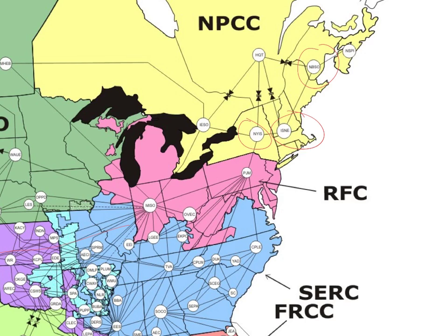What this map doesn't show, and it does show a DC line, this actually doesn't go through Maine. It actually stays above. But right up in here is not ISO New England territory. That is Northern Maine ISO, managed out of Bangor. So there is no direct high voltage connection, 115 or greater, that goes from ISO New England into the Presque Isle area. So if you look at a map, that's considered an island. All its connection goes up and through this way. So it has its own independent system operator in Northern Maine. So from an electrical perspective, Northern Maine is not considered part of New England.